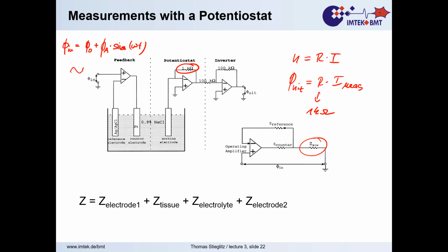One thing that I said, and might probably not have had your full attention, I want to have repeated here. The input voltage should be between 10 and 100 millivolts. Should be very, very small. Otherwise, you are in voltage ranges where you might already induce some reactions that you don't want to monitor. You want to monitor what the material is as such, right?